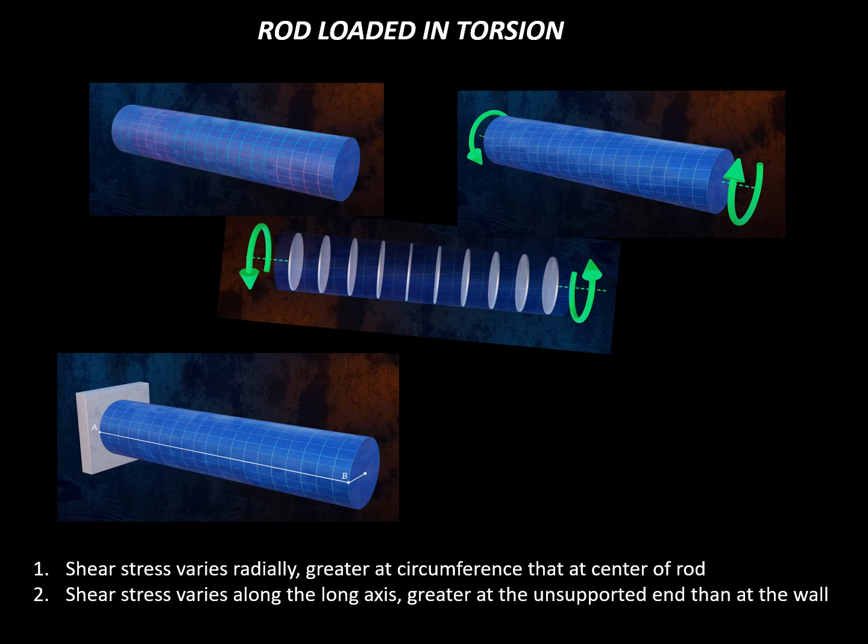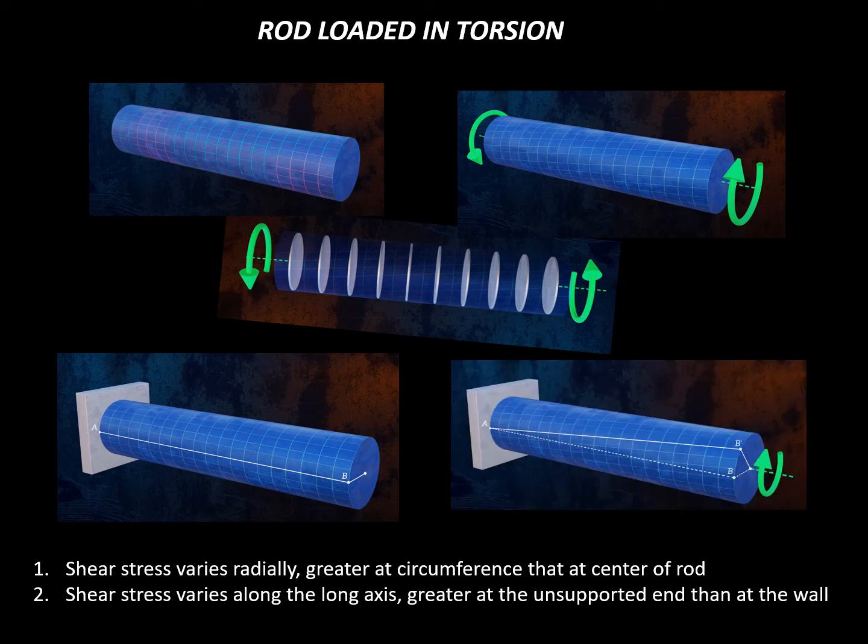So imagine then a plane through this cylinder that runs from A to B and then into the center of the rod. When we grab the end of the rod and apply a torque and twist it, what happens is that the end that's anchored to the wall can't move, but the end that's distal can move quite a lot. And so there's a differential amount of strain that is occurring, right? There's more movement distally than there is proximally to that wall.